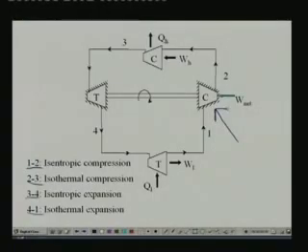Okay. So, the first process, process 1 to 2, as I said, is an isentropic compression. This is achieved in a compressor which compresses the working fluid from point 1 to point 2 in an isentropic manner. In fact, I should mention that it should be a reversible adiabatic compression process, which turns out to be an isentropic process. For this process you have to supply some work input. Let that work input be W1 to 2, and there is no heat transfer because this is an adiabatic process. So, W12 is the work transfer during this process. This is the work input to the compressor.